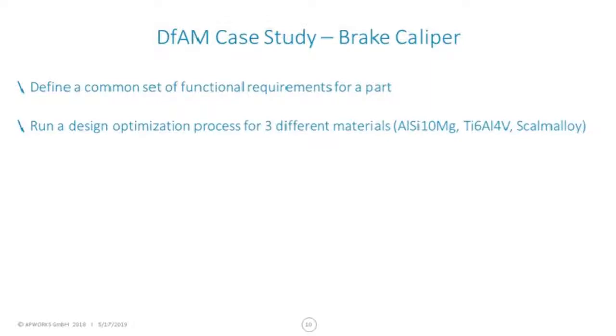Now, if you're not familiar with these materials, the AlSi10Mg is a low-strength aluminium silicon alloy, and it's, by additive manufacturing terms, a relatively low-cost alloy. In the middle, you have Ti6Al4V, that's titanium 6-4. It's a pretty high-performance titanium alloy. It's the workhorse of aerospace for titanium alloys. And to give you an idea, roughly the cost of the powder is 5 times the cost of the aluminium silicon 10 powder.